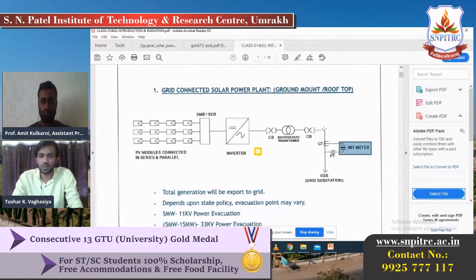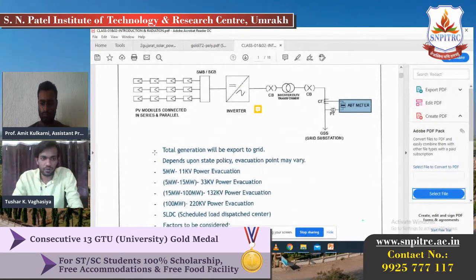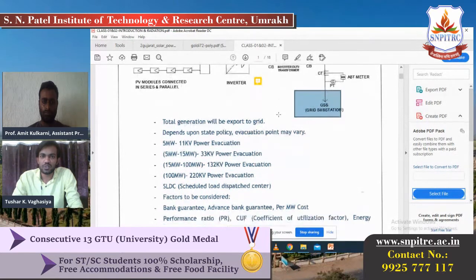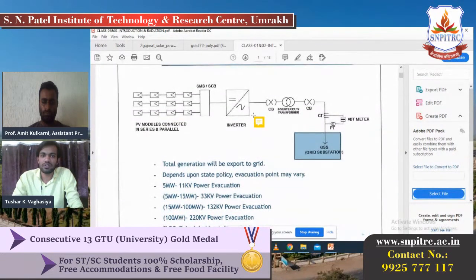The ABT meter shows the generation of the solar power plant for each and every 15 minutes. So this is the grid-connected solar power plant, and as I already told you, the total generation will be directly exported to the grid. Depending on the state policy, the evacuation point may vary: either 11 kV, 33 kV, 66 kV, or 132 kV, whichever is near the station. So we have to use a step-up transformer.